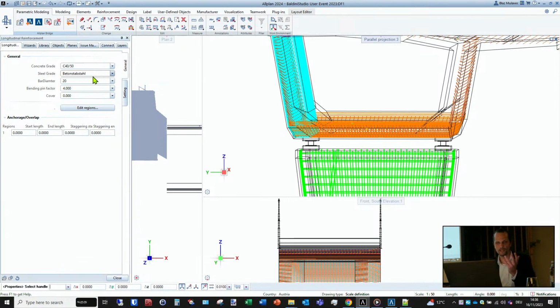For example, what I have mentioned before, in Engineering we still have control over our Python parts which we have placed. We can change, for example, the bar diameter either in Engineering or in Bridge. It depends on your workflows. For example, in some larger companies, production pipelines are usually divided into departments, so that one engineer does geometry modeling, the next engineer does analysis, a third engineer does detailing and plans production, and so on.